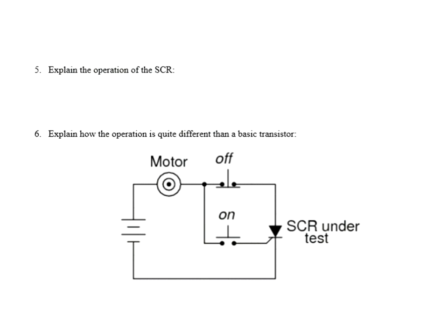That's a tricky question, because in a basic transistor, I can turn on the transistor with the voltage on the base or on an FET gate, but when I remove that controlling voltage, the FET or the transistor will shut off. How does that differ from an SCR? An SCR will not shut off until I remove all of the current from the anode or the cathode.